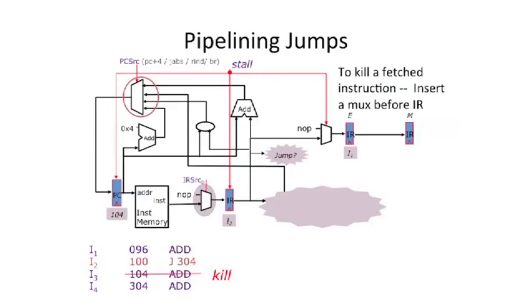And this is what I was talking about before about the extra adder here. Here's our extra adder, which is computing our destination. Sometimes people try to put these two things together, but we're going to take part of the instruction, and take the current PC and add to that, and that's going to compute our new destination of the jump. So here's the control on this mux. We just have to look to see if it's a jump or jump and link, and then we insert a no-op. Otherwise, we actually take the thing coming out of the instruction memory.